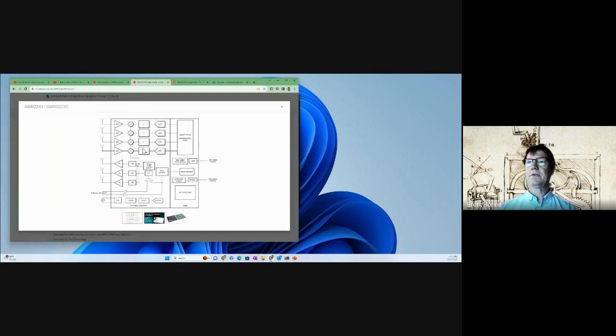And again, the frequency of the signals coming out there are related to the distance of the targets, right? We do some sampling, then we do a digital front end. This is decimating the samples, filtering them, and that type of thing, right? And then you're going to go out to a coprocessor that's going to actually do your FFTs and whatnot.